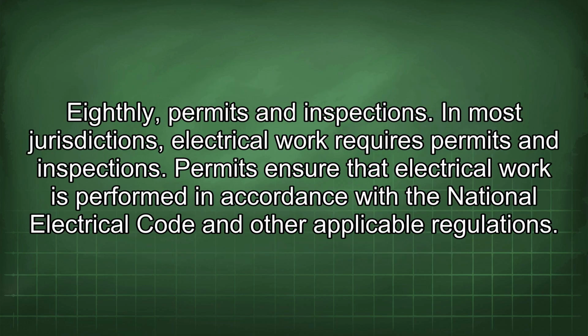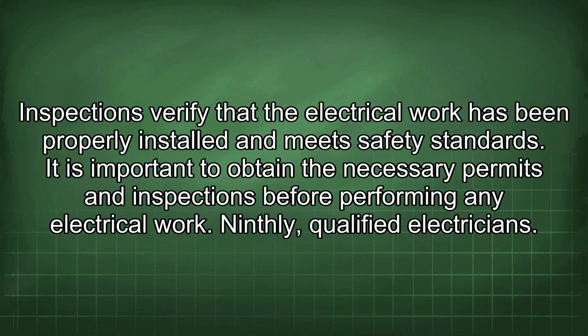Eighthly, permits and inspections. In most jurisdictions, electrical work requires permits and inspections. Permits ensure that electrical work is performed in accordance with the National Electrical Code and other applicable regulations. Inspections verify that the electrical work has been properly installed and meets safety standards. It is important to obtain the necessary permits and inspections before performing any electrical work.